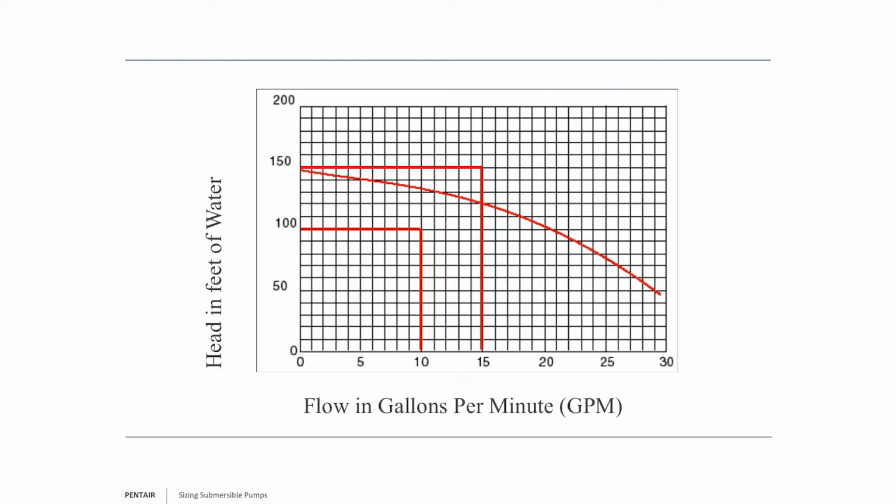For example, in an irrigation system, that extra pressure might mean the heads might miss. Might mean that you get overlap of arc, or you're watering the neighbor's lawn for free, for example. So you have to ask yourself, what will it do? Will it in fact maybe possibly damage one of the irrigation heads? Okay, so we have to ask that question.